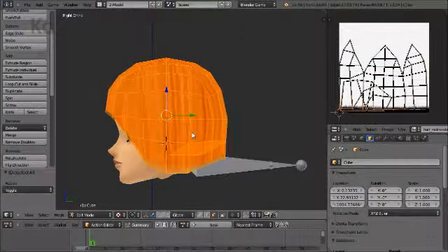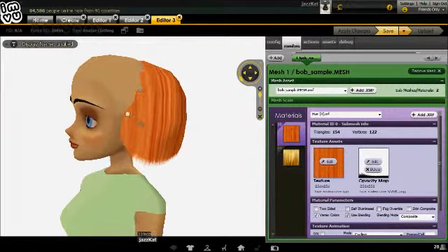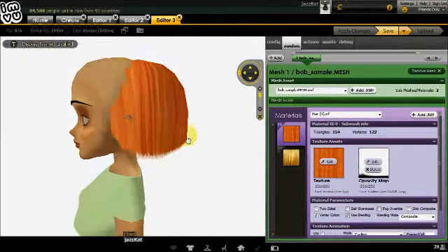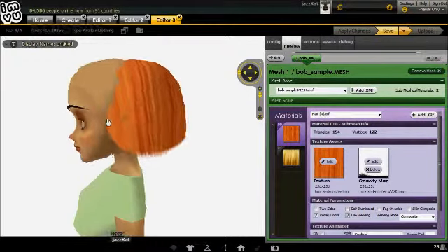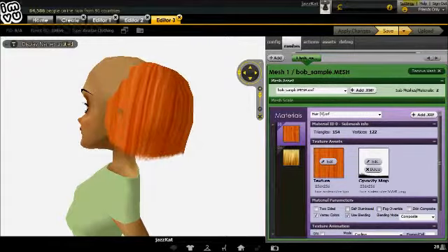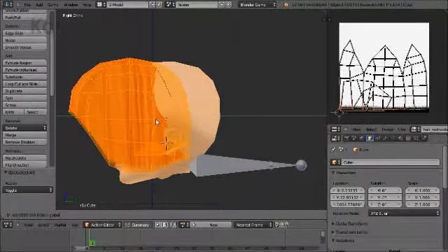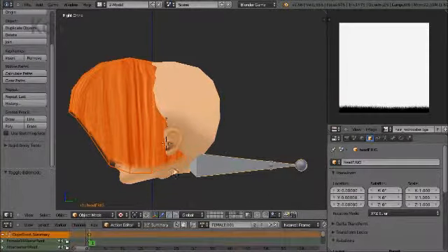So as mentioned, back in Blender, edit mode, select everything, and relative to how the mesh appears in IMVU, observe where this line is and how far the hairpiece needs to be adjusted or moved forward or back, left or right, up or down relative to the head. So I need to adjust that about that amount. Re-export.